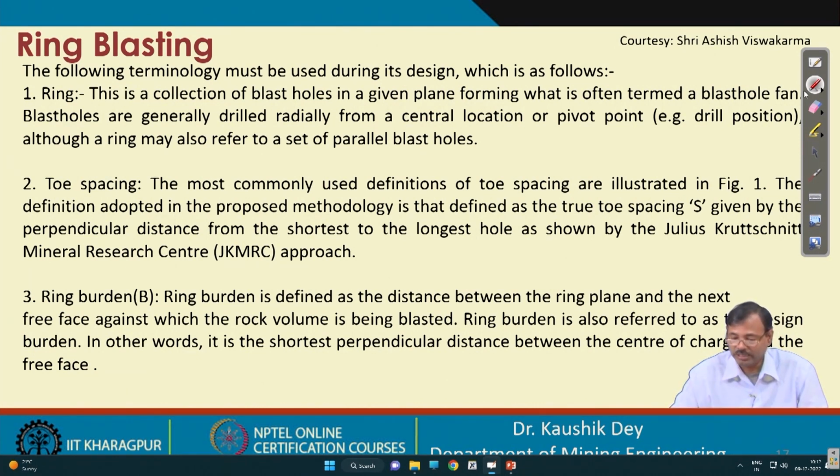However, burden is the same, but burden is not distributed throughout the face. Burden is concentrically distributed, in the mouth part burden is not there. So, that is why horizontally up to 180 degree it has to be considered. That means, from 0 to 180 this angle must be properly drilled to achieve the excavation in the full burden.